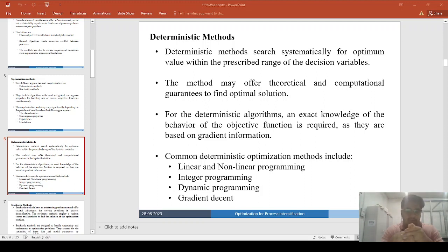So there, if your flow is in the Stokes regime, because convection is not a dominating phenomenon, your entire mass transfer will be diffusion limited. So you might then simplify your system by cancelling out certain terms, the inertial terms, in the species conservation equation.